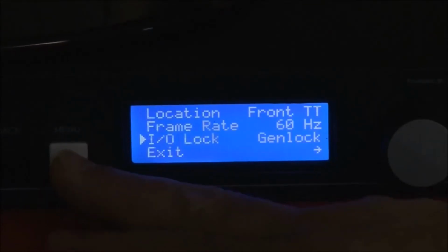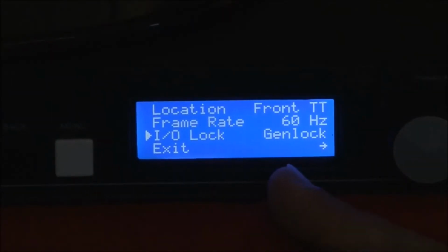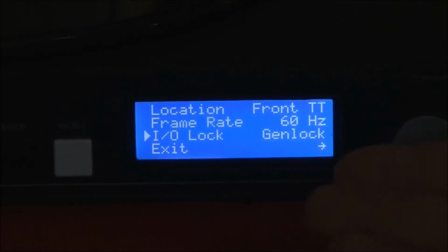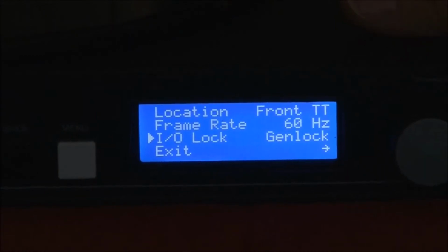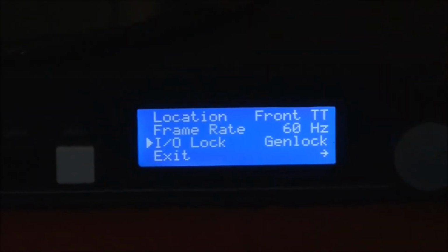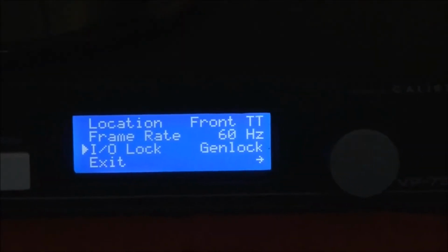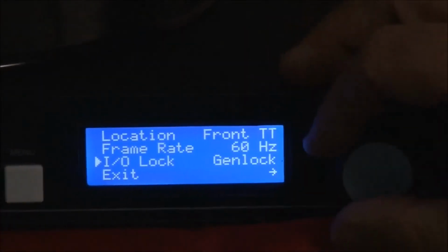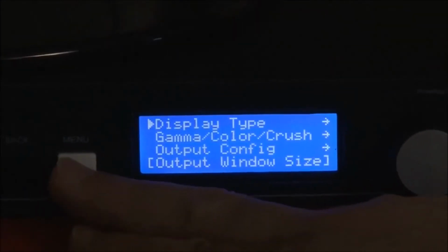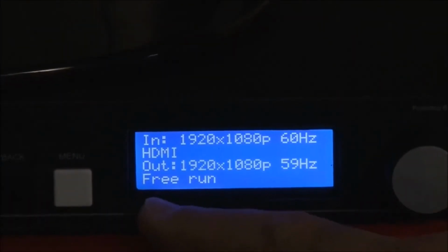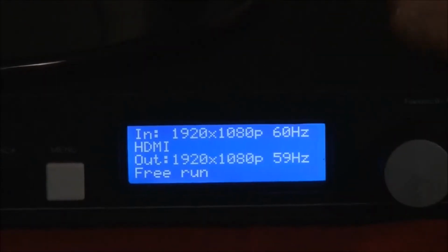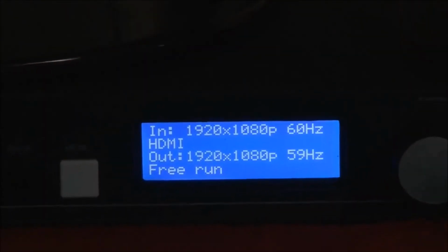Normally in scalar switcher mode you would leave it in Genlock. That means if you connect a Genlock reference it will use it and clean switch with that, but otherwise it will clean switch by generating its own output timings. If you select auto or you select source, the input switching is not clean. So now we're in Genlock mode and we haven't got a Genlock signal, so it's free running, which means the 794 is in control of the output timings.